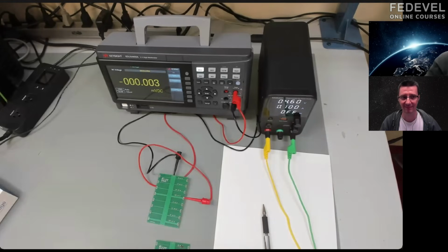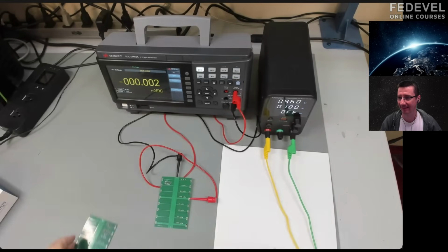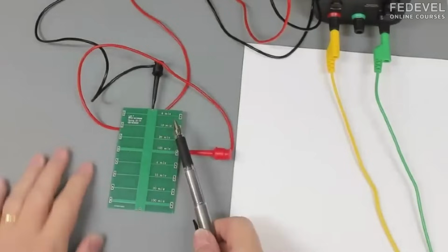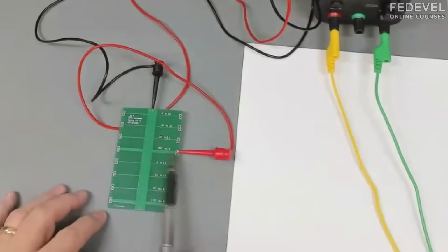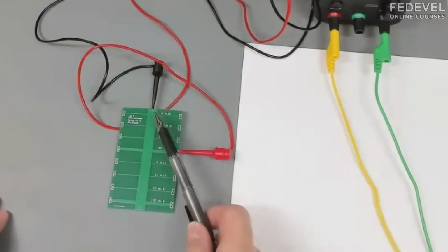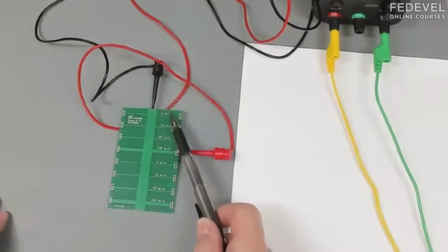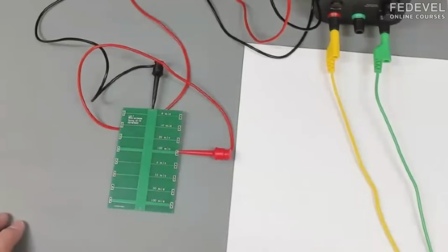We're going to come to my lab here. So we're in my lab, and I have set up a test board that we use in one of my classes that is designed to measure the resistance of different line width traces. They're all 1 inch long, so the number we'll get is the resistance per inch. They're different line widths, from 6 mils up to 100 mils, and they're replicated down here, so we have more variety to use.